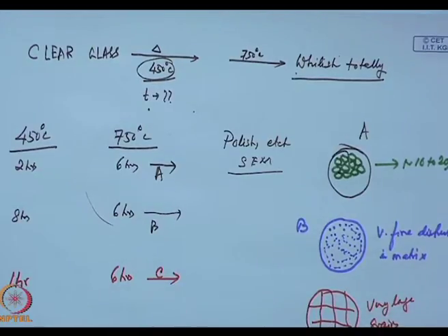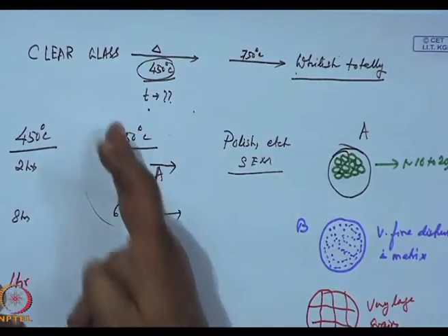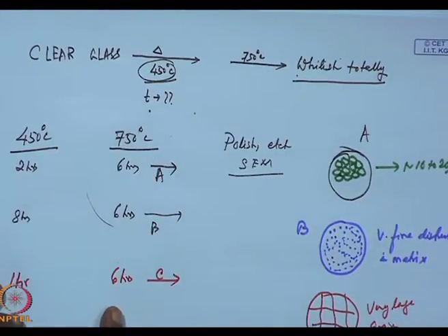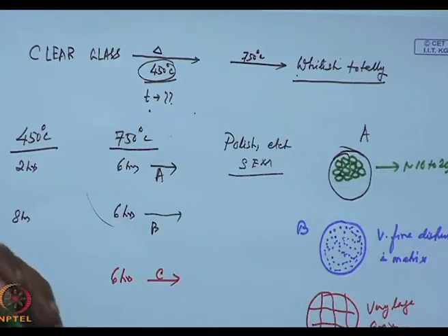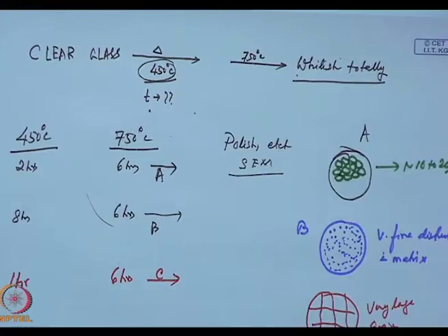So, what is happening? Why is this temperature kept constant? So, why are the sizes varying? The simple reason is, if you look at Li2CO3 SiO2 phase diagram, you will see that over there there is a phase separation occurring.